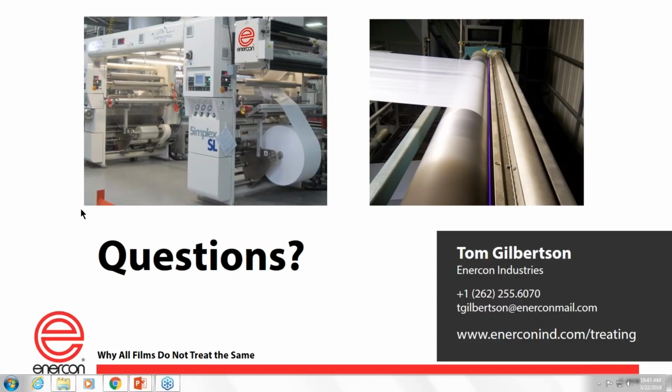So Tom, we have a question on calculating the watt density level when you have a segmented treater, for example, a 600 millimeter wide treater where they're not treating the 200 millimeters worth of the film. Do they calculate it by electrode width or the active electrode width? In that case, when you have a segmented electrode, you're always going to calculate the watt density based on the active amount of electrode width. Always the active amount.